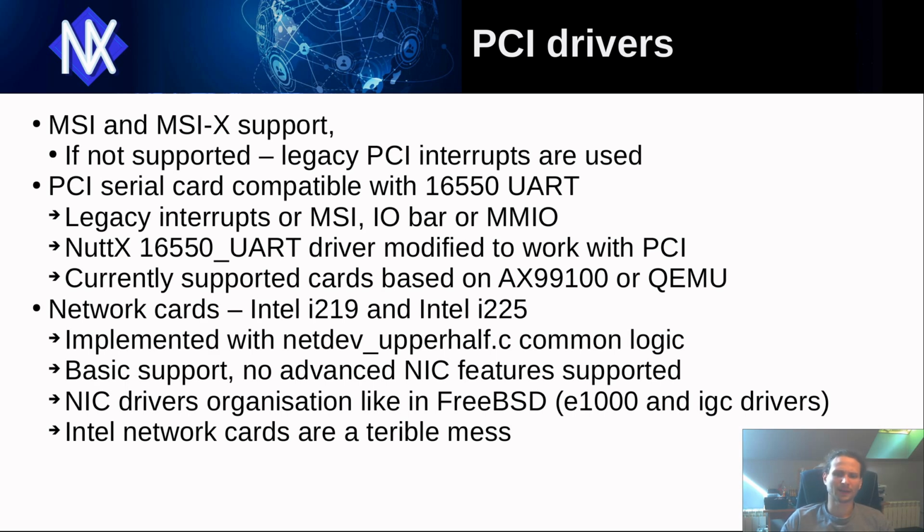MSI support required some improvement to x64 interrupt logic, such as support for all possible interrupt vectors and dynamic vector allocation. To communicate with real hardware without a legacy UART port, it was necessary to implement support for PCI serial card. Currently, cards based on AX99100 and QEMU simulated PCI serial device are supported.